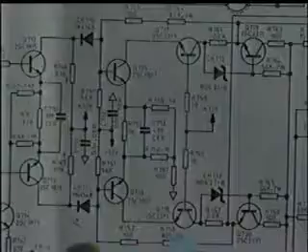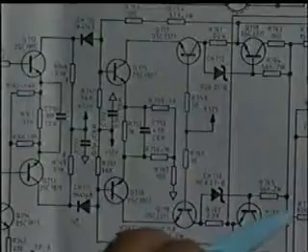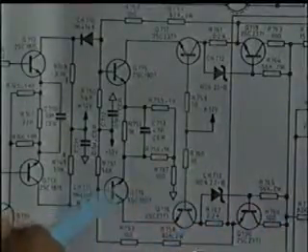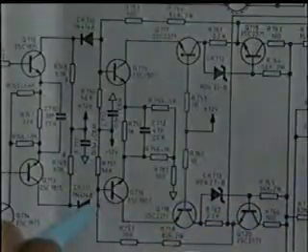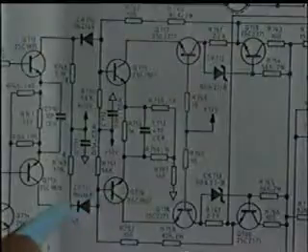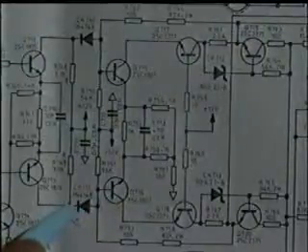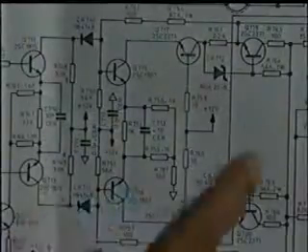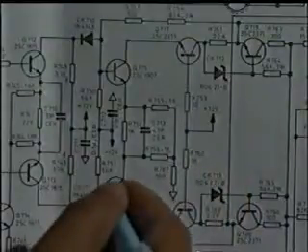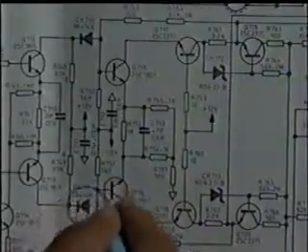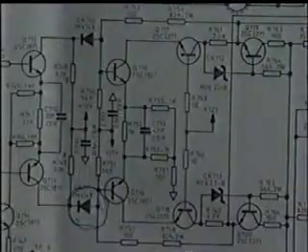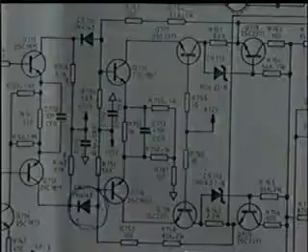Here in the circuit, this X1 plate is not getting the sawtooth up to this point, where the sawtooth is available here. This shows this component seems to be defective. Remove it and confirm with a good multimeter.